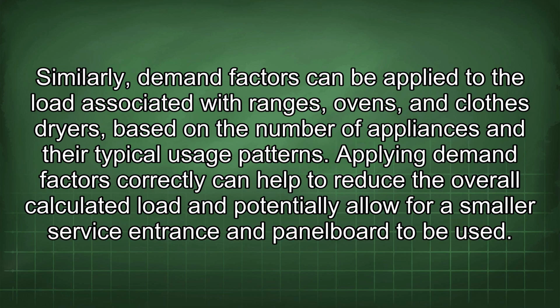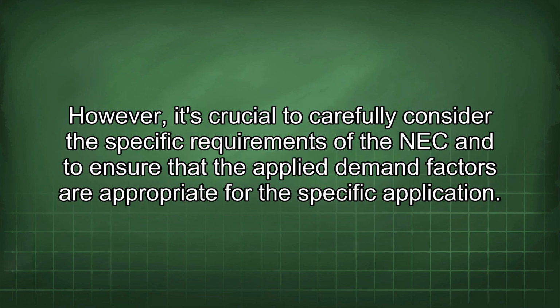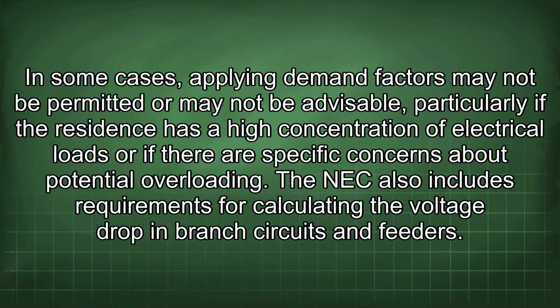Applying demand factors correctly can help to reduce the overall calculated load and potentially allow for a smaller service entrance and panel board to be used. However, it's crucial to carefully consider the specific requirements of the NEC and to ensure that the applied demand factors are appropriate for the specific application. In some cases, applying demand factors may not be permitted or may not be advisable, particularly if the residence has a high concentration of electrical loads or if there are specific concerns about potential overloading.